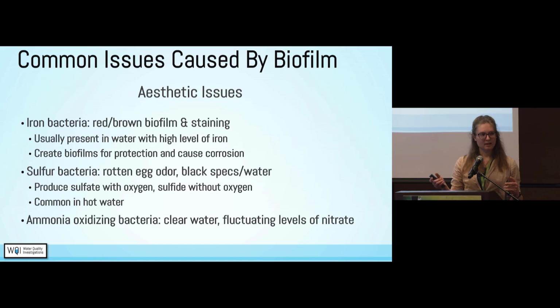What we saw is that the nitrate was actually close to 12 in their well, and it was close to 5 or 6, if I recall, in their aquifer. And so we advised them to do a well cleaning, and I think it's just amazing how much I've seen that doesn't seem like it should be possible, and it is. But then they actually didn't need to do nitrate removal because we took care of the problem that was happening in their well.